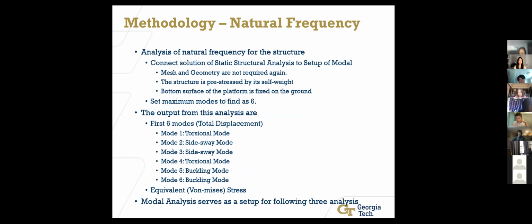And for the natural frequency, we analyze the model for the structure, like the modal analysis. We first connect the solutions of the static structure analysis to the setup of the model and mesh. If we do this setup, the mesh and geometry are not required again, and the structure is pre-stressed by self-weight, and the boundary condition is the same as the previous one.